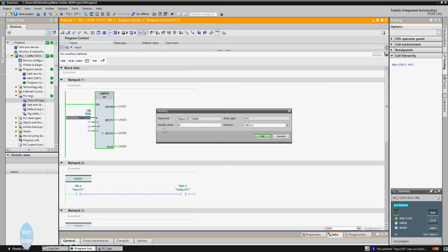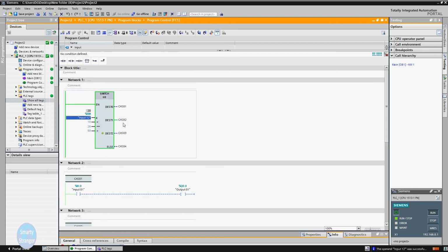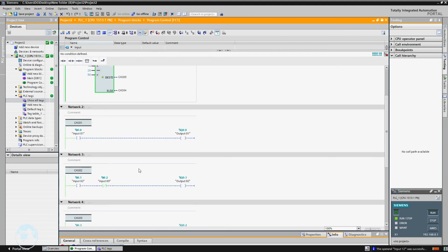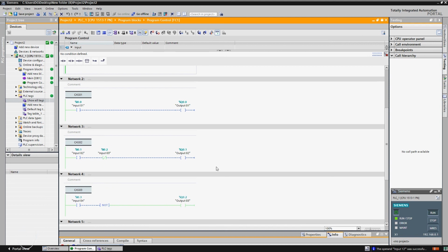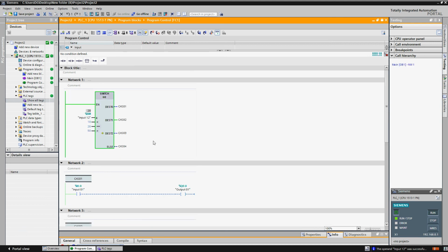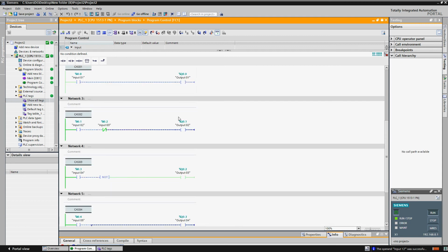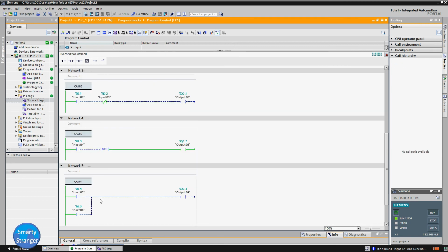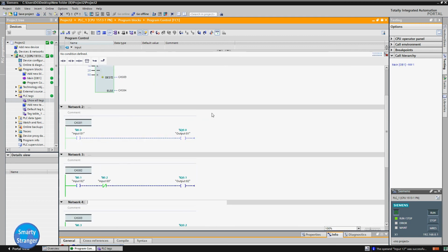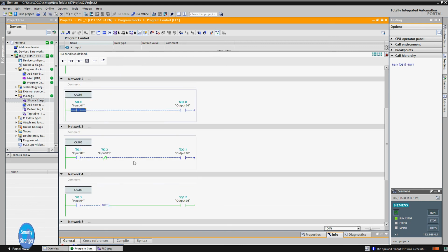Now we are applying a value of 20 at K input. The instruction compares the input with the defined limits. Here you are seeing that it enables the second output CAS02. It means execution of the program will start from network 3, and network 2 has been bypassed. Here you are seeing that we can apply high or low signal on all inputs in all networks, except network 2.